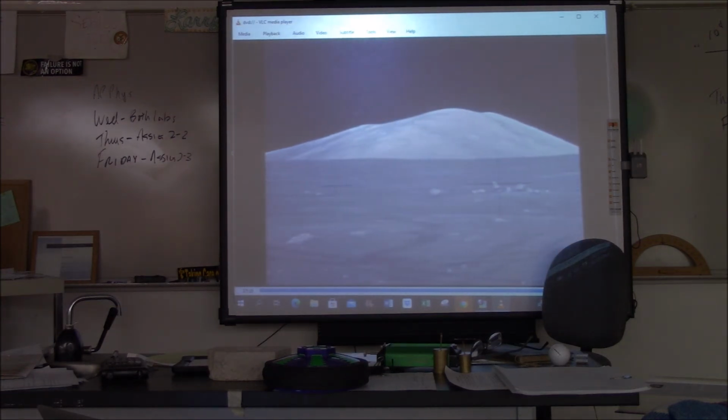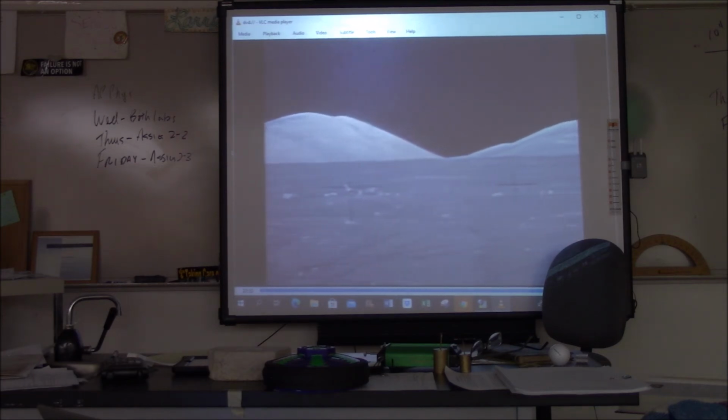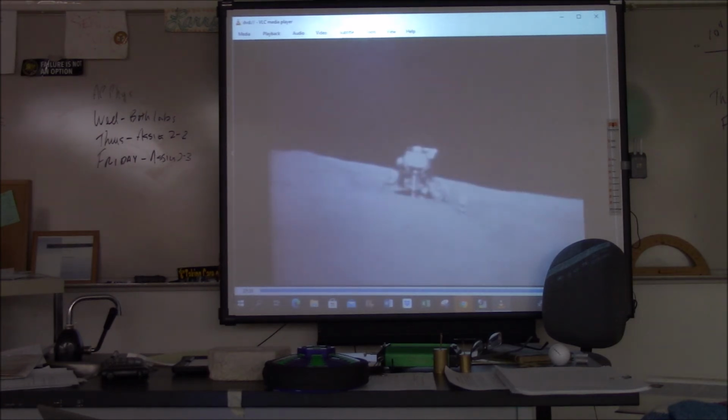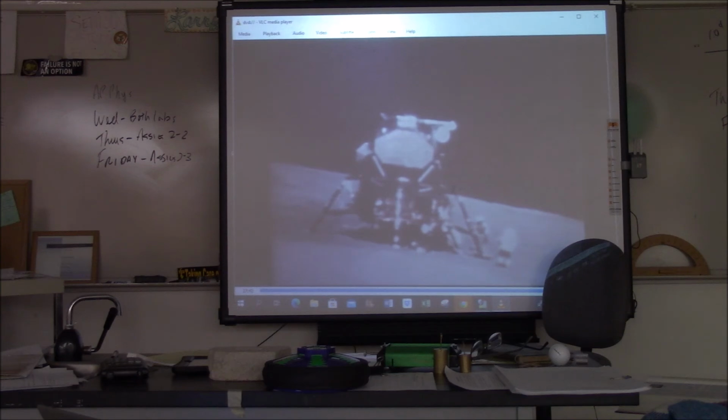The black sky during the daytime bears witness to the fact that the Moon possesses no atmosphere to scatter sunlight. Because of the lack of any atmosphere, frictional stress and drag are non-existent as the launch from the Moon's surface occurs. In contrast to Earth launches, streamlining of the spacecraft becomes unnecessary, as the lunar module's protruding components in a non-streamlined configuration is of a functional design and presents no problems during launch.